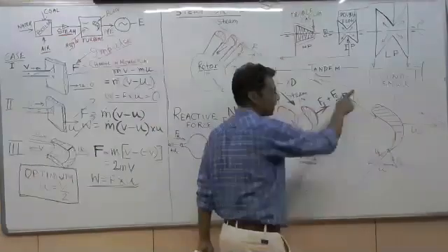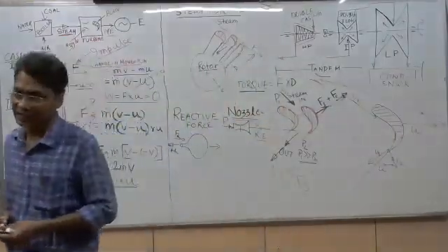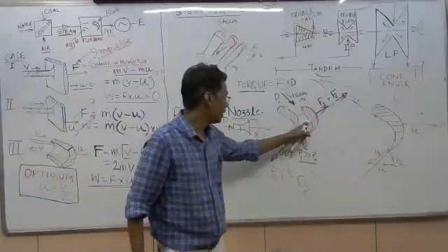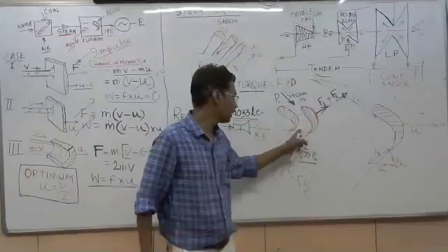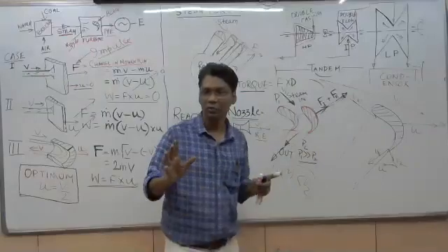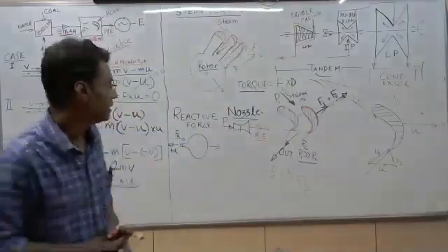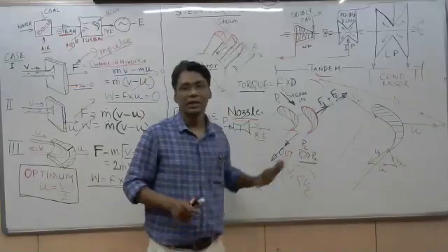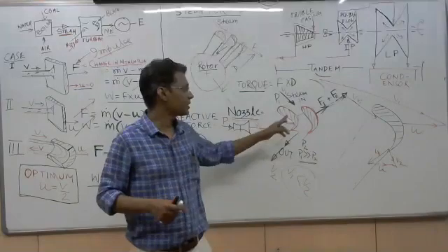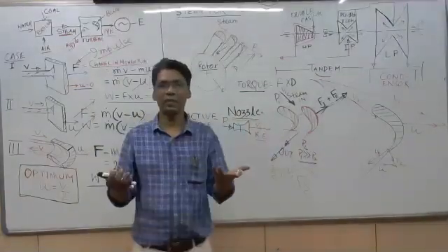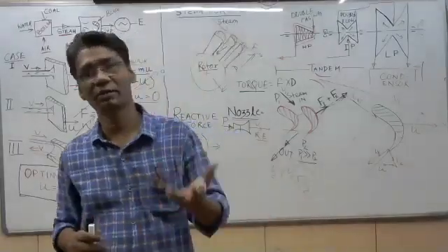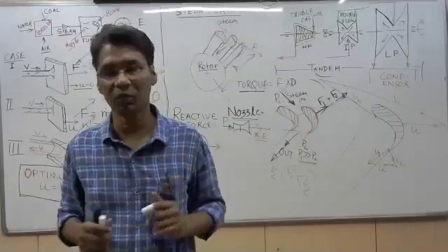There are two component forces. The force is increased by the design of the blade, in such a way that the reactive blade profile gives a nozzle-shaped area, and we are getting two kinds of forces. So that is the impulse-reactive blade design. The blade cannot be 100% reactive because there is a change in velocity. So steam turbine blades are mostly impulse-reactive blades. It is not 100% reactive or 100% impulse blade. It is a combination of both.